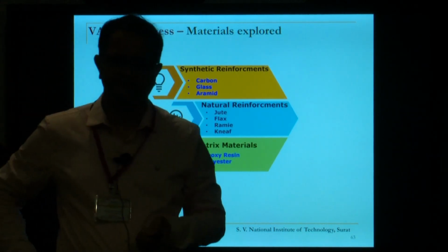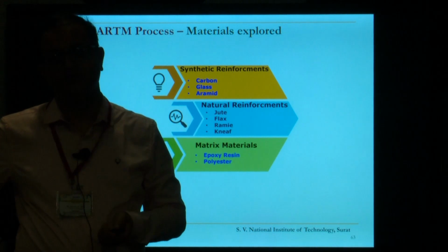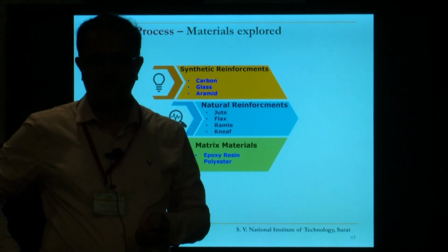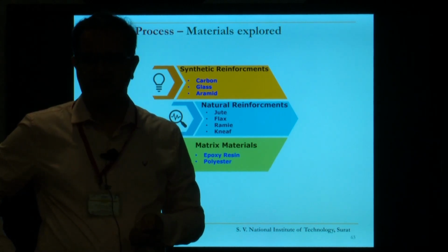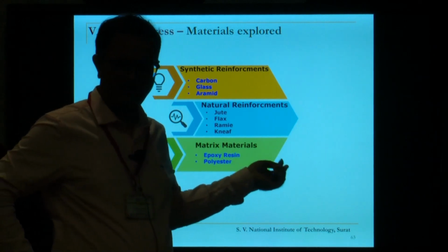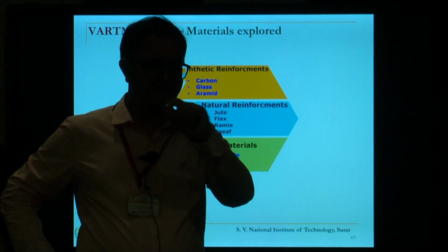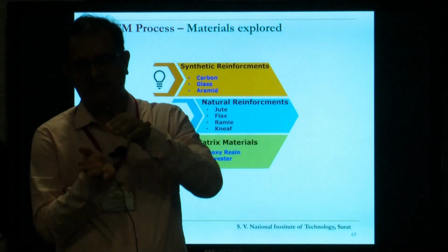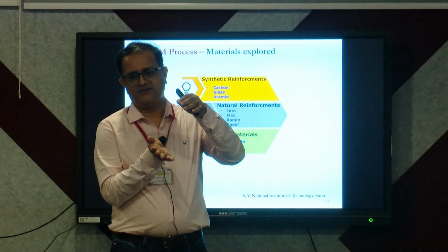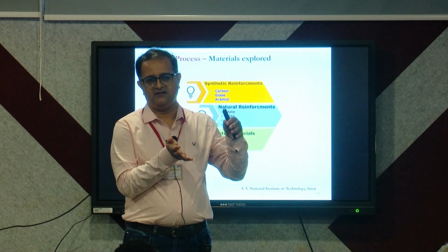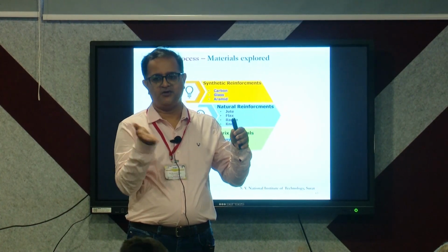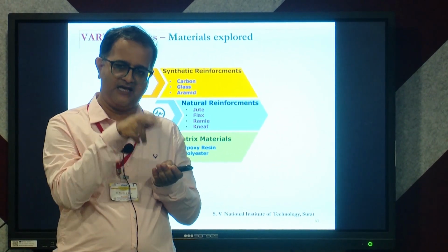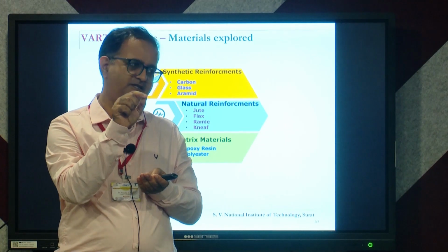It depends upon the number of layers you decide. Say, for example, as per the ASTM standard, I don't remember exactly, but suppose your requirement is that the thickness should be 2.4 mm. To generate that 2.4 mm you need a certain number of stacked layers, and that never came to our mind, and in our case the cost of fabric increased because of that. So 12 was the ideal number. If you set 12 layers of carbon fiber or glass fiber, it will give you the required dimension.